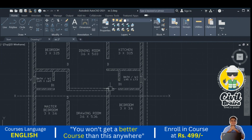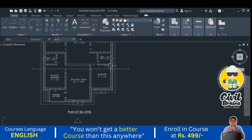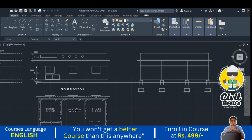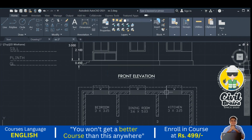So here there is a full opening. If it is considered an opening, then if you cut this section and stand and look here, this window will be visible, correct? This window we need to draw here. So how to draw that one? We can directly project here also, but it is not exactly above that. So just see the distance. What is the distance of the window from the corners? That is 1.05 from the left corner, and from the right corner 1.05.